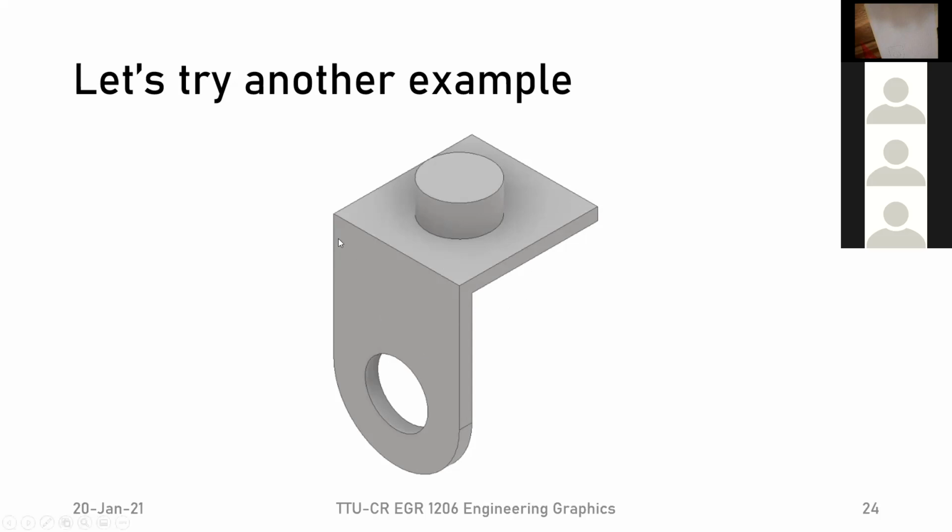All right, so now we have our front view almost done. There are a couple things missing. The first thing that's missing is, of course, our cylinder. If we're looking at the front view, we can see the cylinder. It becomes something that sticks up out of our page. So all we have to do is draw what will look like a rectangle, because we'd be able to see an edge that goes down here, and the same on the other side, and the height across would look like a flat line going in this direction.